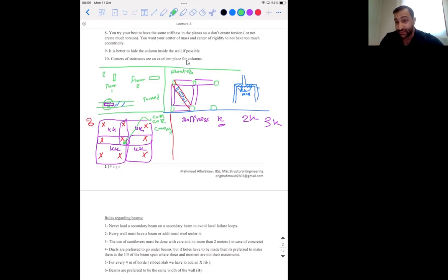If I don't have that, then I'm going to have some eccentricity where the building will be like this. Center of mass is here and center of rigidity is here, and we have something called eccentricity. Distance in meters. There are discrepancies between them, and that's not fun. That's basically torsion on the building. Torque.